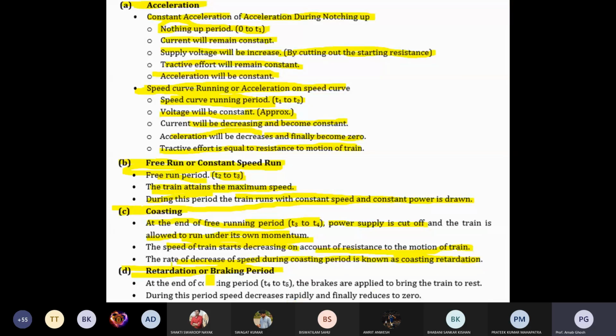Okay, so then you are using magnetic braking, that I am telling you. So vacuum brakes are there, air brake, vacuum brake, then magnetic locking. Okay, after some duration when train speed is less, then you can go for that magnetic braking, or dynamic braking. It means additional energy now you have to dissipate through the resistance connected across your motor.